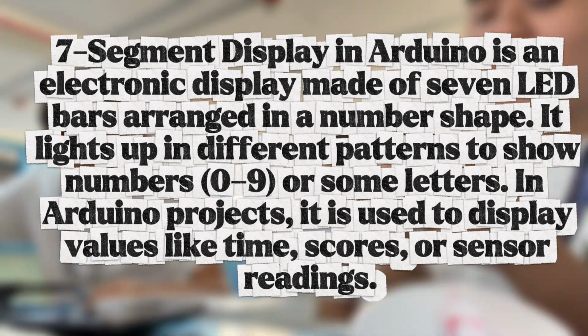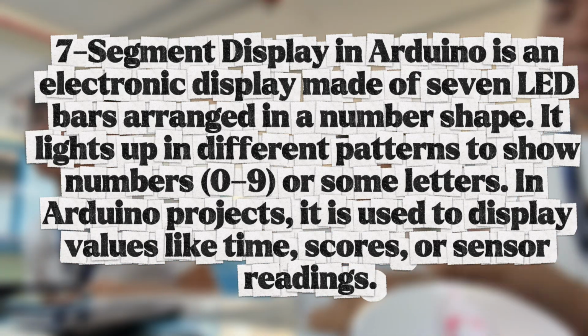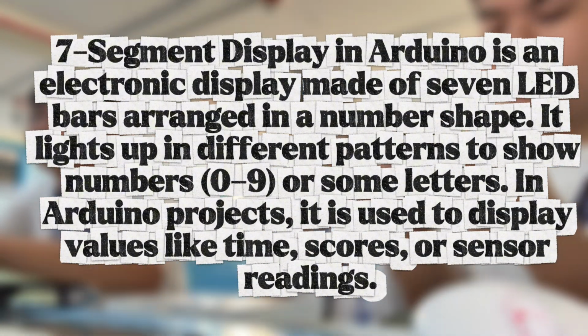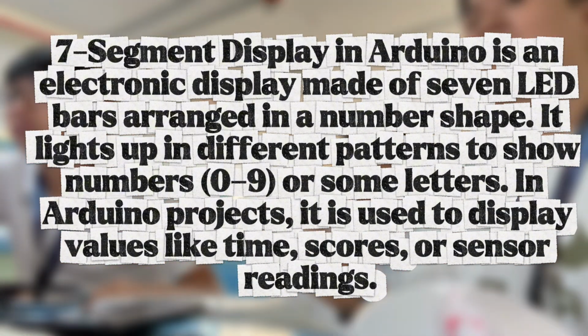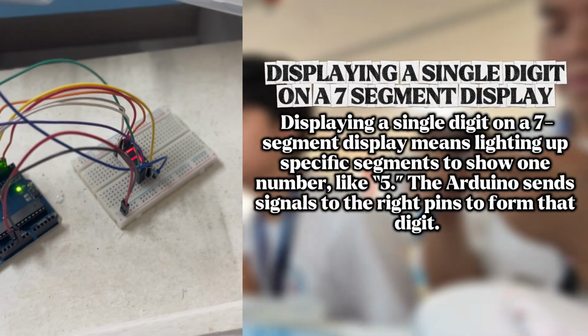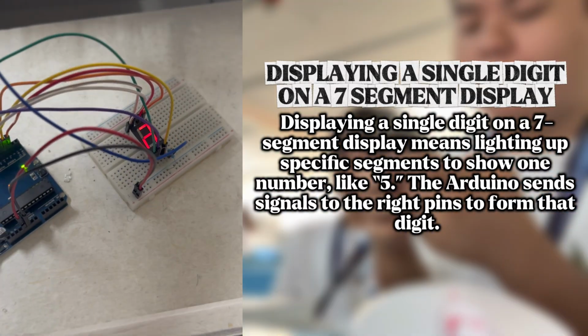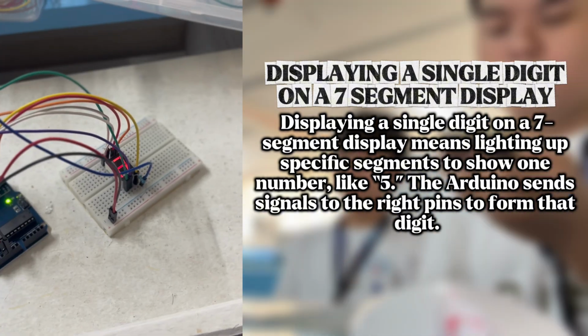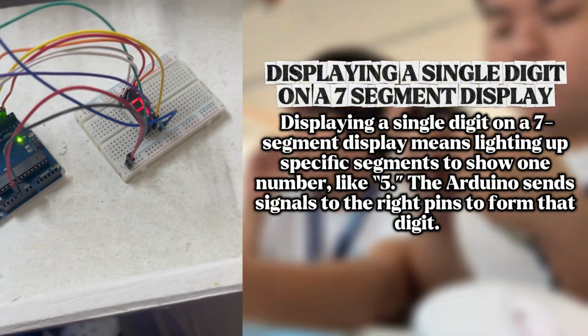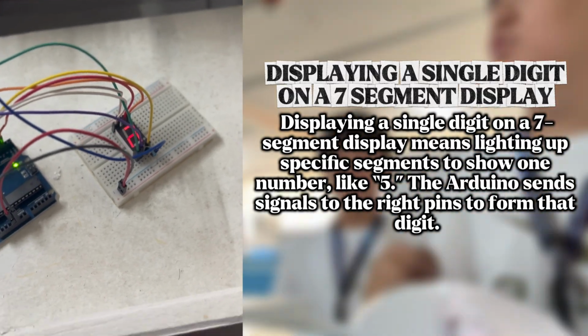A 7-segment display in Arduino is an electric display made out of 7 LED bars arranged in a number shape. It lights up in different patterns to show numbers 0 to 9 or some letters. In Arduino projects, it is used to display values like time, scores, or sensor readings. Displaying a single digit on a 7-segment display means lighting up specific segments to show one number like 5. The Arduino sends signals to the right pins to form that digit.